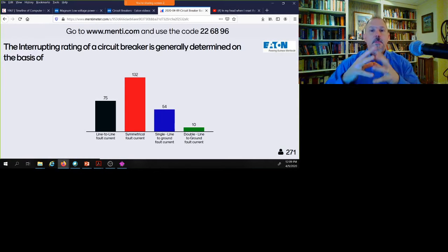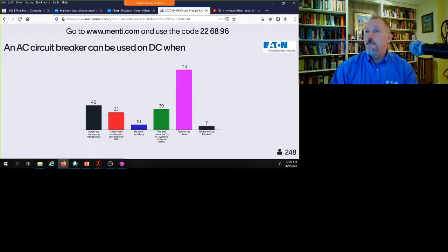So we talked about all the different types of fault currents, and there's reasons you'll calculate different fault currents in the system to understand how overcurrent devices may function and operate. But when we talk about the interrupting rating, we're looking at that symmetrical 3-phase bolted fault current, or whatever that symmetrical highest fault current is. It could be the line to ground fault.